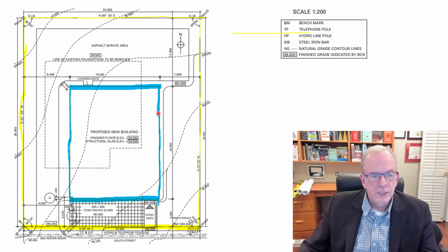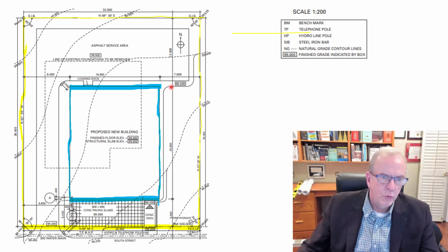All right, so we can see where the building is set back from. We've got these different locators here. And yes, because this is 20.8, as I said, that tells you this is the setback from the north property line to the building, 12.6 meters. So now you know those locations. So we can locate where the building, and this is the exterior building walls, are going to be located. So basically the outer part of the foundation wall.